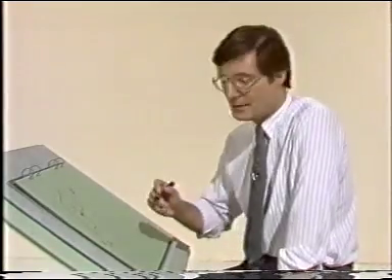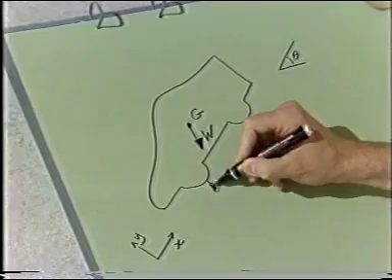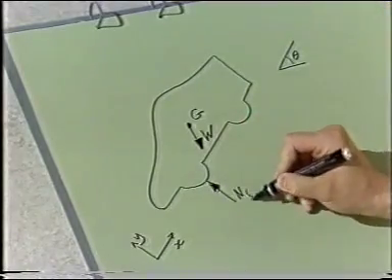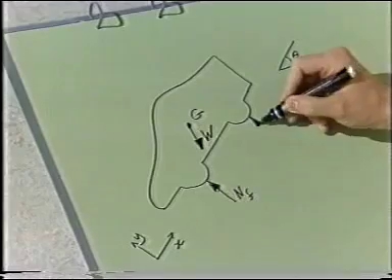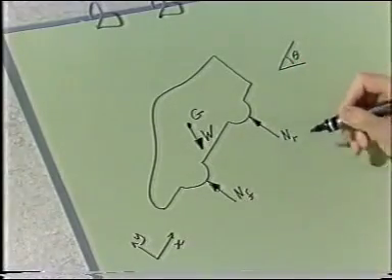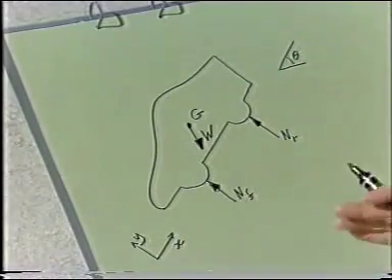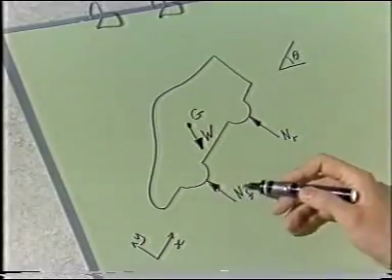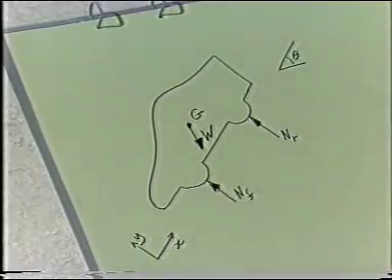Now, from our list of possible forces, what about stiffness forces from solid contact? This gives us a normal force at each wheel, actually caused by distortion of the tyre and ground. The term normal has a precise meaning. It means perpendicular to the surfaces at the point of contact. So I'll draw on front and rear normal forces. Actually, of course, there are 4 wheels, 2 wheels on each axle. So NF is the force on the front pair of wheels.